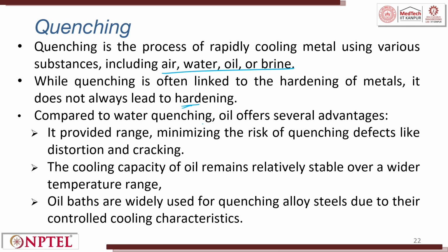Compared to water quenching, oil offers several advantages. Because when you quench in water, the heat gets transferred to the water, the water starts bubbling and then it forms a jacket around it. Once it forms a jacket around it, the performance is different. So, oil quenching is always preferred.